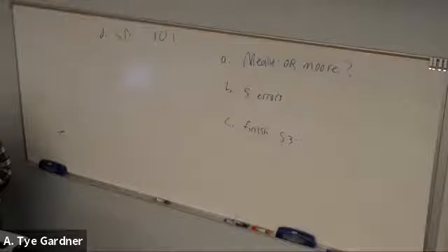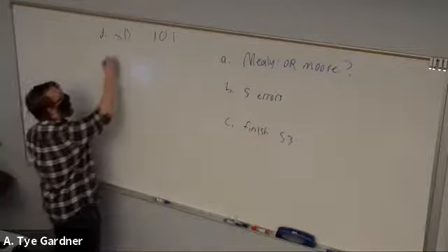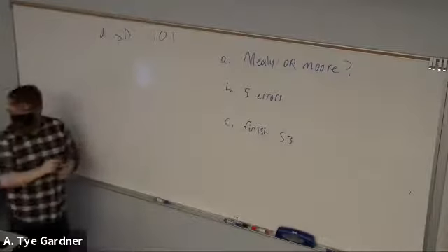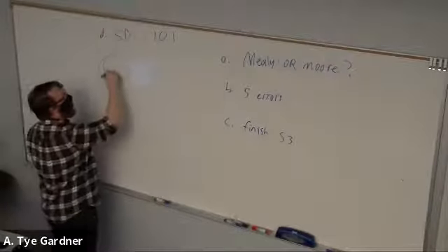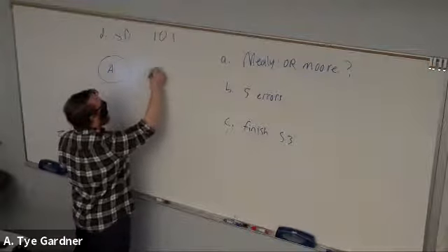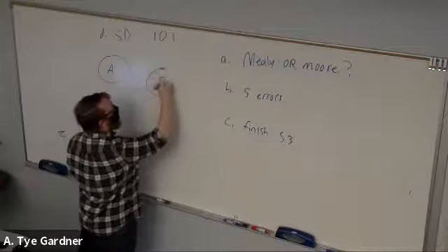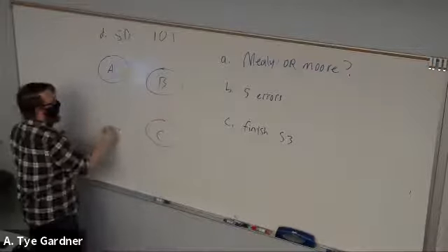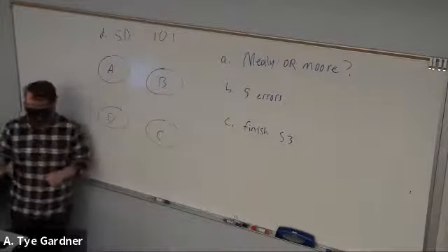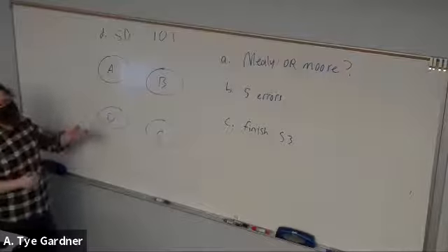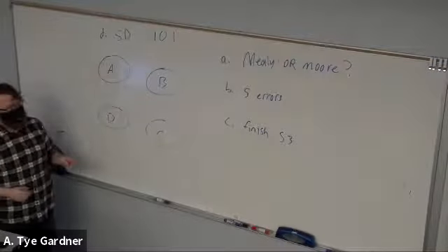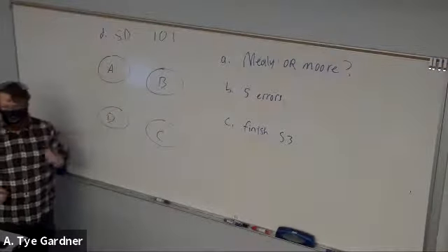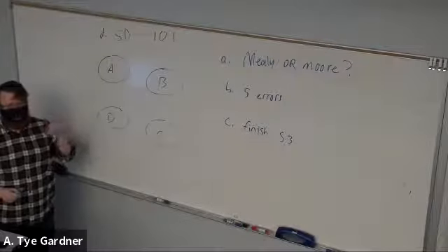Because otherwise we're going to have a hard time writing the state diagram for this. If it's Mealy, we're A, B, C. And if we're a Moore, it's A, B, C, D. How do I know that? Well, in a Mealy state machine for a sequence detector, it takes the same number of states as you have in your sequence. If it's a Moore, it has one extra.